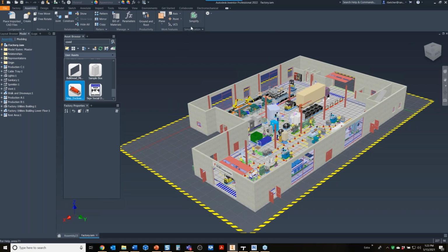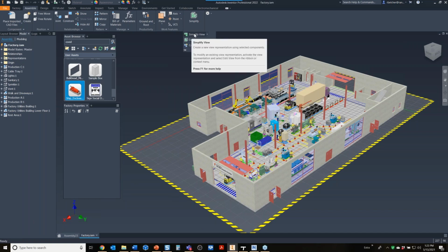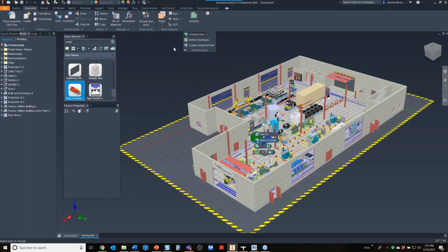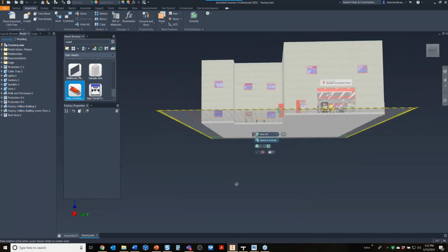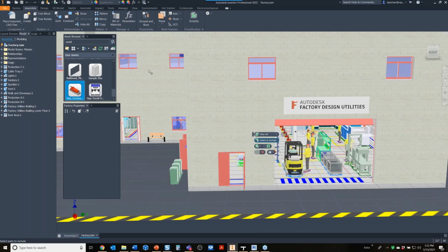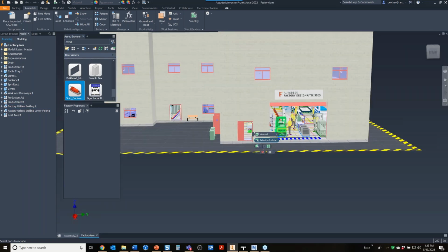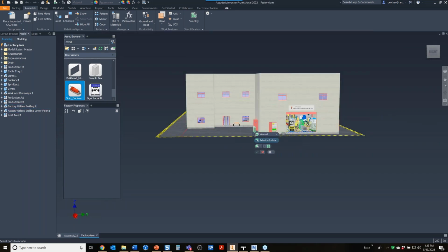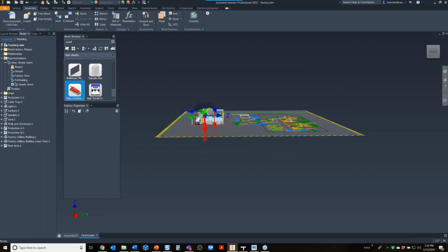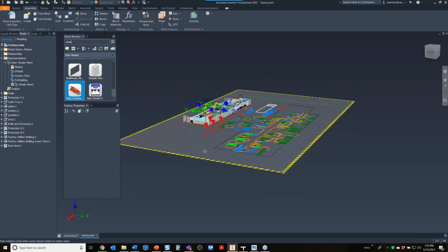Now, a couple of things I could do before I ever get started here is do a Simplify view. A Simplify view just means that you want to select the components that you really care about. In this particular case, I just care about this overall subassembly over here. I'll tell you what, I'll use production level C then. That's the one I care about right in there. And I'll click the OK button, and that should turn off everything else except for that bit of information.